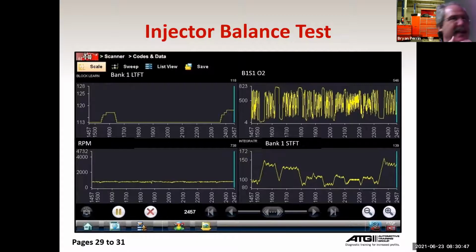So at that point, I went in and actually checked the resistance on the injector and found that it was out of specification. And the circuit was okay. But again, kind of interesting how it's in the details. But do you follow the logic I used to get there?